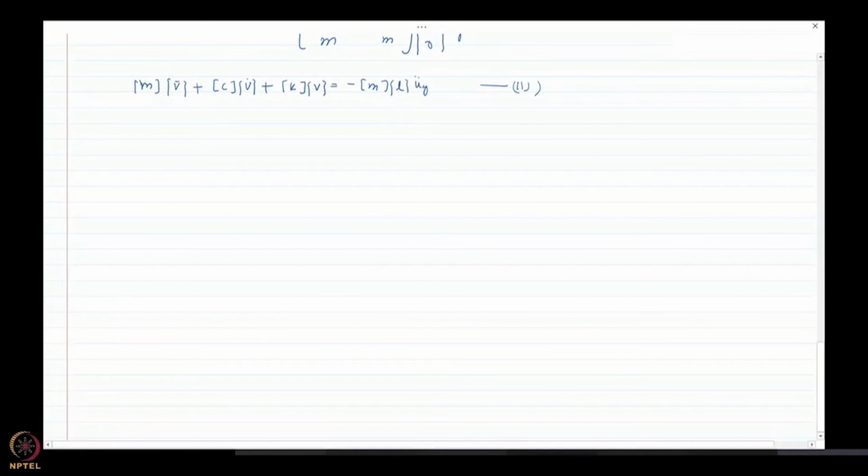So what I'm going to do here is consider the superstructure as a fixed base with mass m and stiffness ks, and this is a single degree of freedom representation of the superstructure. For the fixed base superstructure, I can find the frequency as omega s equal to square root of ks divided by m, and damping as cs divided by 2 m omega s.